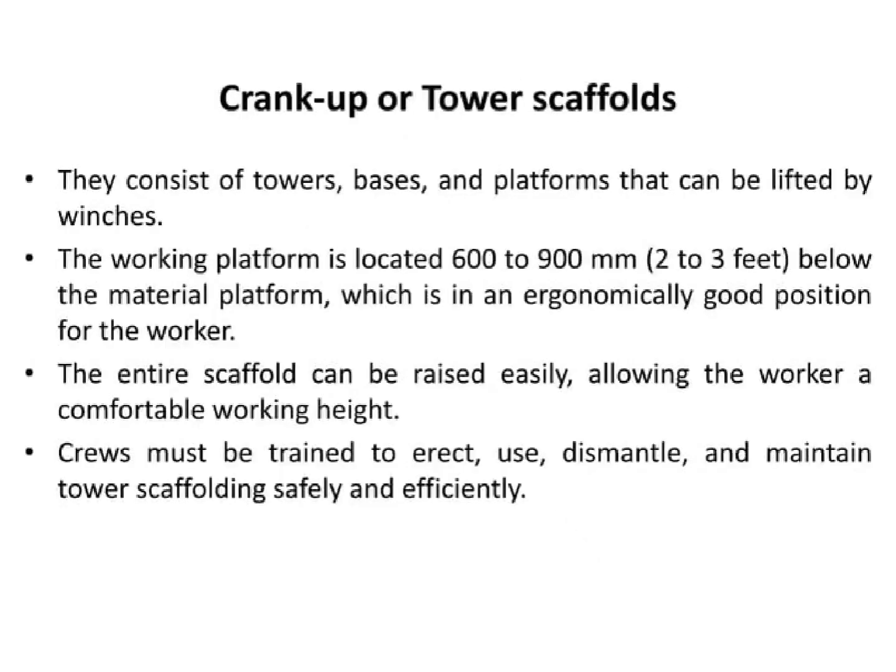Scaffolds of the crank-up or tower variety are important pieces of equipment at construction sites. They consist of towers, bases, and platforms which can be raised using a winch. In between the working platform and the material platform lies a space of 600 to 900 millimeters, 2 to 3 feet. This height is ergonomically suited for the worker, allowing them to work in a relaxed manner. It is critical that crews are taught how to properly assemble, use, and dismantle the scaffolding in a way that is both safe and effective.